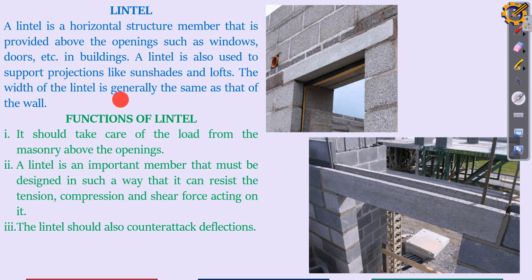The width of the lintel is generally the same as that of the wall. That's it. As you can see this one here, you can see the width of it. See this one too, width same as that of a wall. It should take care of the load from the masonry above the openings. Masonry is referring to what? Block or bricklaying. Take note.